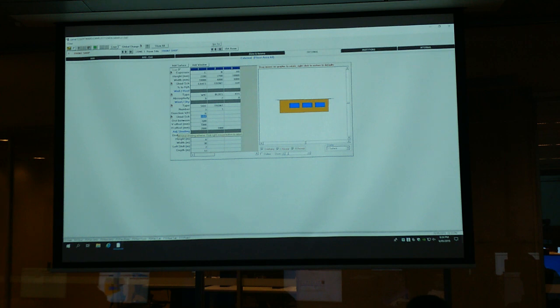But in this part, you need to define the location, the position of the windows, by playing with these numbers. And also the shading scheme numbers, the position as well. When this number changes, the location of the windows will change. So that's for the external wall parts.